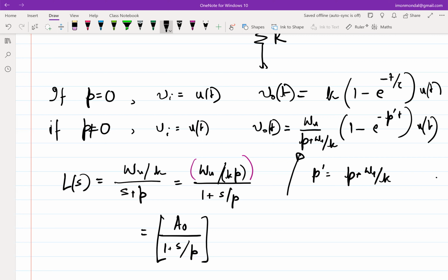Okay, so that's why you will see that almost all commercially available amplifiers give you the UGB of the loop under some condition. Which essentially means that if you operate below the UGB of the loop, you will get the required output. If you operate above the UGB of the loop, it will not work.